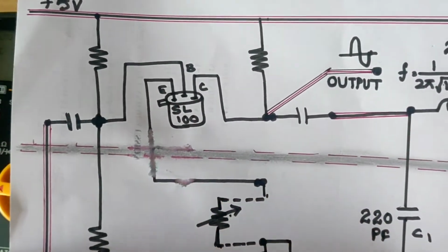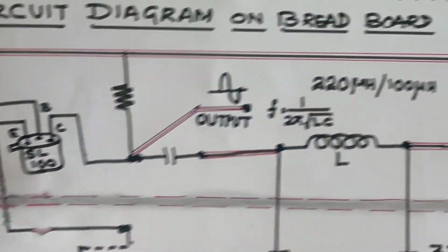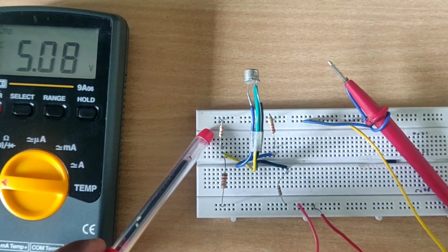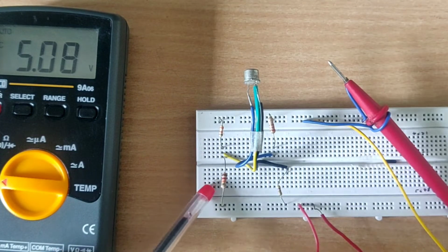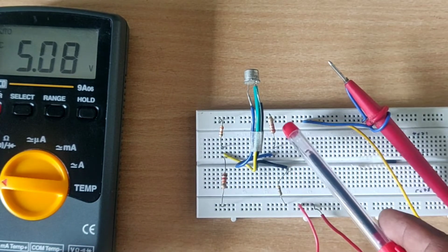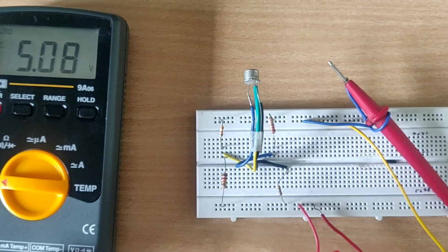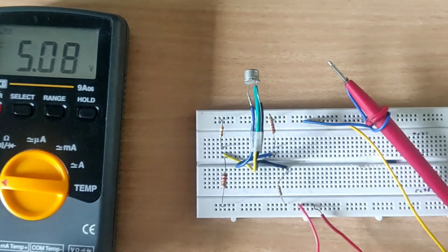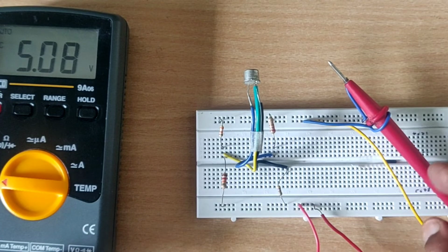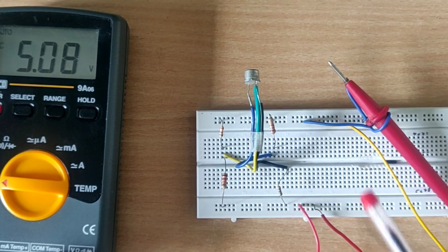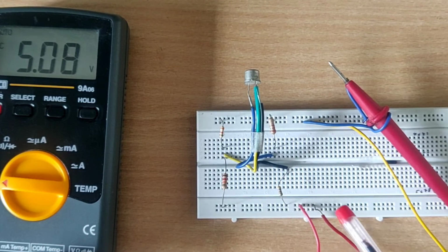Now I am going to show you practically how I assembled here. You can see that. So as in the circuit diagram, R1, R2 and RC and RE. No capacitors are connected because we have to measure the DC conditions. Now you see that I connect with respect to ground. This is ground connection. I switch on the power supply and set the VCC because my design is 5 volts.